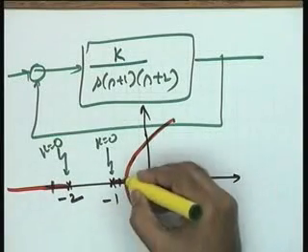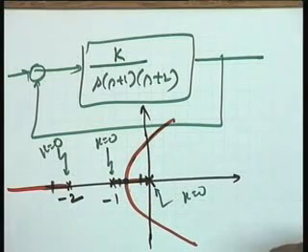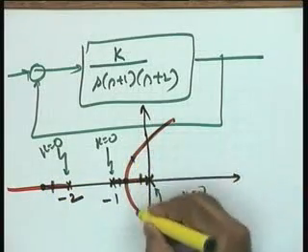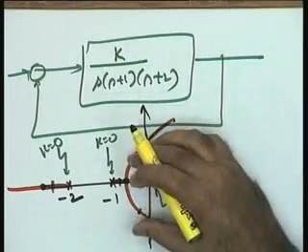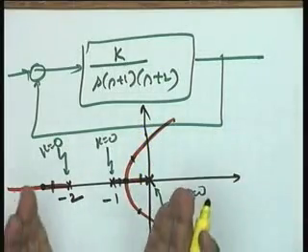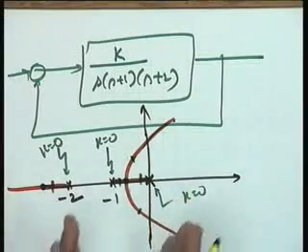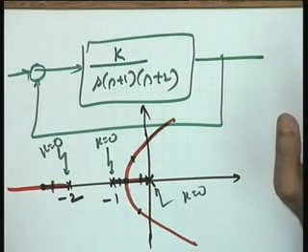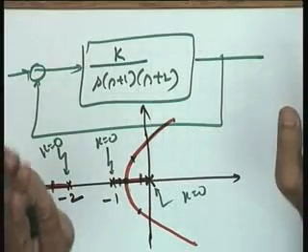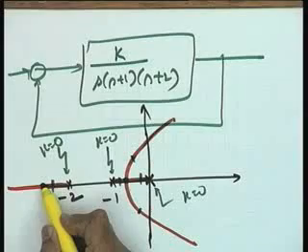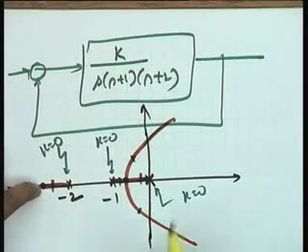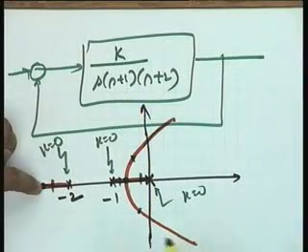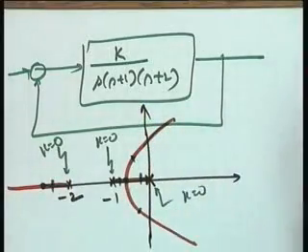Increase k further, you are reaching this particular point where the two roots are repeated and real, and let us say the third root is here. Further increase in k gives you complex conjugate roots. Okay? Now you see that this system clearly shows, as you are increasing the value of k, you are drifting towards the imaginary axis, and the system is going more and more towards oscillations and instability. And the third root also gives you the location. You can test the dominance condition and see whether the contribution of the third root on the dynamics of the system is going to be significant or not.